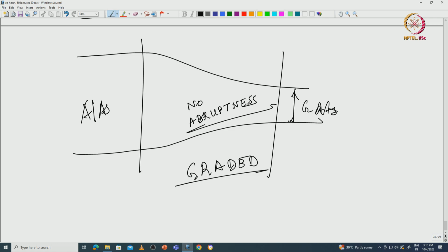So this is a graded heterojunction and this is very interesting, because when the band gap is continuously decreasing, you see the band is bending like this. Let me choose the blue color maybe. If an electron is here, it will roll downhill this way, correct? So the electric field is in this direction for the conduction band, for electrons.